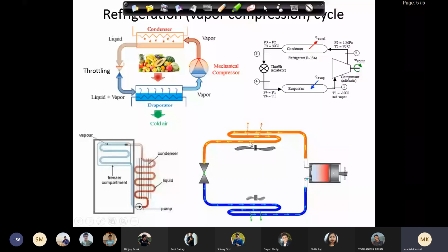What I am trying to show is that heat is getting extracted in the evaporator, down here, okay, and then that vapor enters this compressor. You can see this compressor is compressing the gas. Why do we compress the gas? So that its pressure increases, okay, and of course enthalpy also increases, because you are working on the gas. Rather than pressure, we should say enthalpy increases. We will see the equations. Through equations we will get a better understanding of what is happening where.